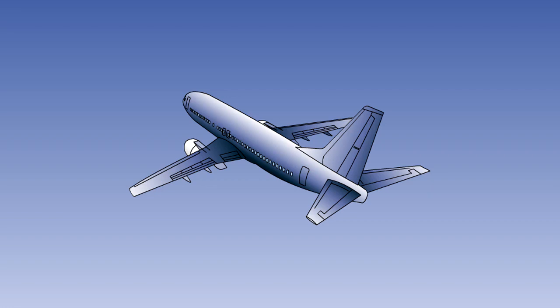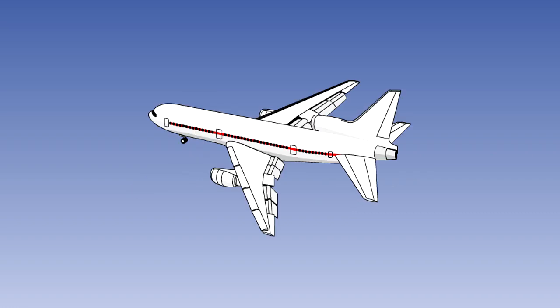In this lesson, we will look at thermal ice protection systems, as used on many turbojet aeroplanes, including the Boeing 737. A thermal ice protection system is one where the surfaces to be protected are heated. One major advantage of this system over mechanical systems is that there is no change in the profile of the surface being protected.